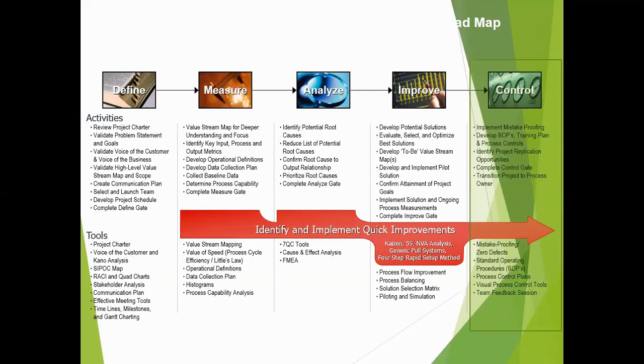And in measurement system analysis, what we do is we try to identify what the measurement system variation is. So even before you collect the data, you fix your gauge, you fix the operators, and you minimize that variation so that from the total variation, you only have process variation left, which is something you can go ahead and study further. So keep that. Okay.